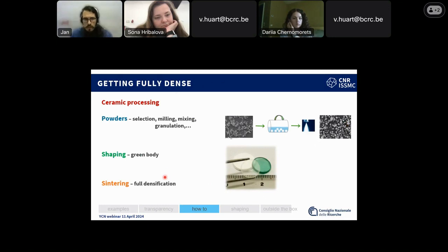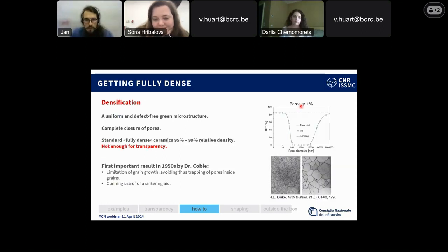And nowadays, there are also other systems where instead of yttrium oxide, you may have gadolinium oxide or some other stuff. The point is, I do have a difference in refractive index, but if the wavelength is long enough and the particle size is small enough, I actually get some transparency. And this, of course, applies to many other systems in principle, as long as they're not miscible. And in the same way, it can apply to materials that are not cubic, that are not optically isotropic.